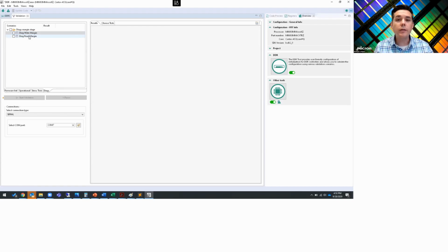On the read side, the LPDDR4 device is the one outputting data, and the i.MX mini is then changing where it strobes that data and also changing its reference for its receivers to paint the data eye and show us what that looks like. One advantage to a vTSA compared to a pTSA, that we'll talk about again later, is the fact that I can actually do an accurate read margin measurement using a vTSA. The reason is that I have control through the tool of parameters that are on the controller side. On a pTSA, I'm measuring everything on the DRAM, which means I'm not going to get accurate results for what the read eye looks like. Here I can get accurate results because I'm modifying parameters on the controller itself.